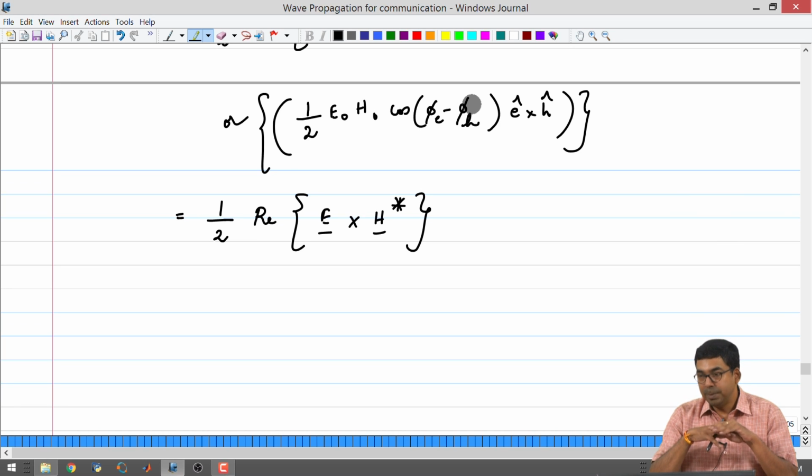In the case of a pure inductor, we know that V is equal to L di/dt, which means that you will have voltage and current out of phase by 90 degrees. More specifically, the current lags the voltage by 90 degrees in phase, and then when you take VI cos phi, you will get 0. That means that your inductor cannot consume any power. There will not be a power transfer to a pure inductor.